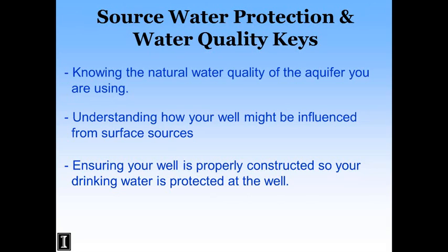The other thing is understanding how your well might be influenced by surface sources, and I'm going to go into these in a little more detail here, and that means that your wellhead's protected, that you keep sources away from your well as far as you can. You know how vulnerable your well might be based on the geology, the depth of your well, and where the source water for your aquifer comes from.